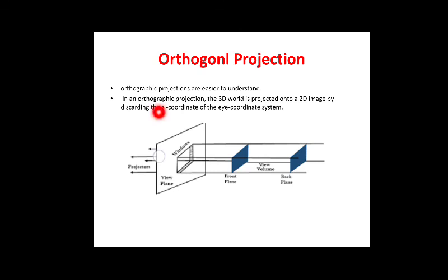So this is the view plane. You are putting that object onto the view plane. The point of intersection is the projection of the vertex. So what is the intersection point here? The vertex's intersection itself, and then we connect these projected points by line segments, and we are representing that part onto the 2D plane.